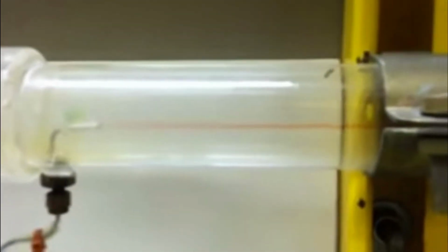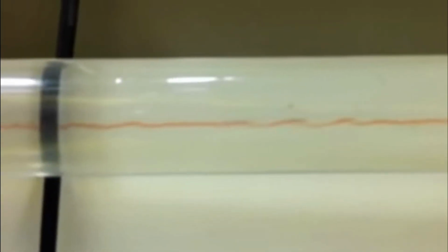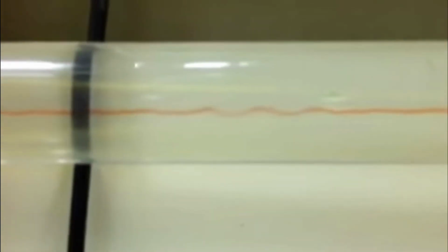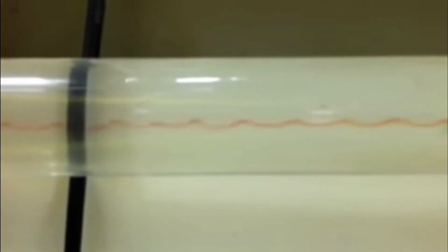And as it's looking at the effect of going downstream, what you see is that it starts off, I don't know if the velocity is being changed, but if you change the velocity of flow in this pipe, instead of being laminar flow, which you can think of as a pack of cards skimmed across each other, the flow will become full of vortices. It'll get turbulent. And so this typically scales with velocity. As you start with a very slow velocity, it will be laminar. Every particle travels exactly parallel to each other.